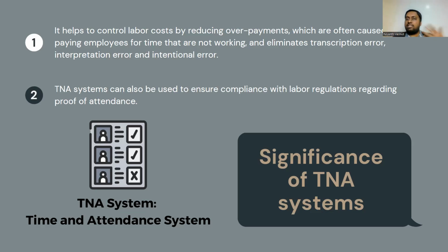If a masonry wall can be constructed by just 4 masons, but you have got 6 masons, that means 2 masons will be sitting idle, but they will be charged, or they will be paid as well. Those 2 masons normally charge around 800 to 900 rupees per day. So let's say 900 rupees. If they're a head mason, 1000 rupees. So 1000 rupees per day, the client or the contractor has to pay for those 2 extra masons. Imagine you do that for 6 or 7 days. You are paying a huge amount of money, which is waste.